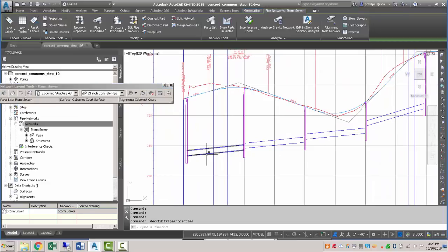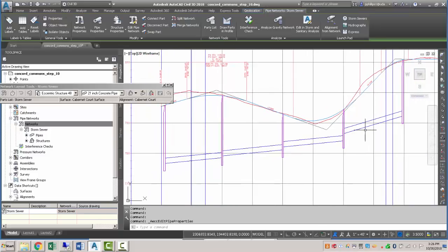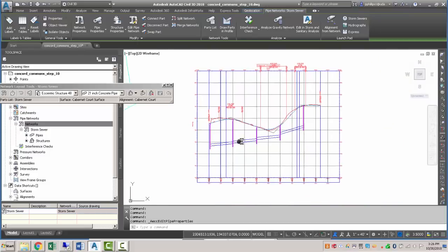Obviously you would want to be sizing these based off of your hydraulics and water resources instructions. That way we can actually quantify the amount of water we have to capture and what size pipes we need and how we want to set the locations of where all these pipes intersect with our manhole structures. But this is the basics here.